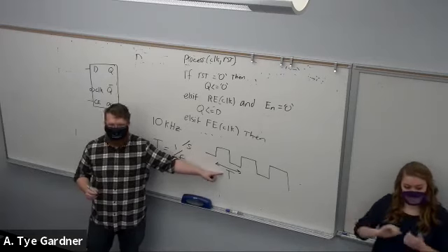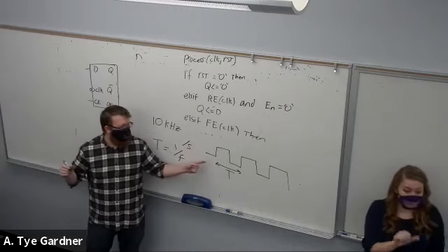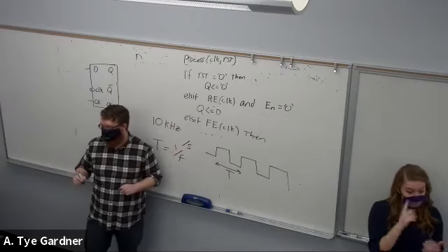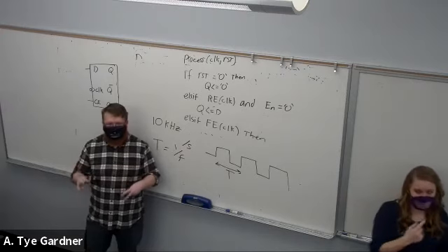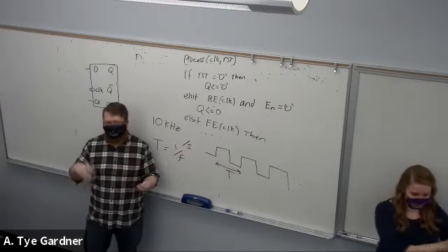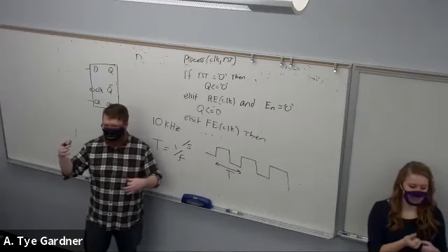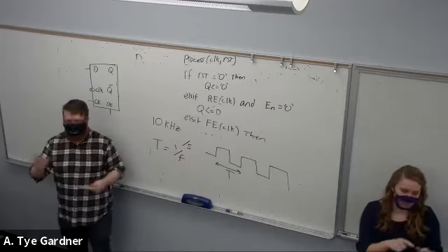That's why you can't write 10 nanoseconds. It doesn't know. But what you can do is count the number of clocks, wait for 30 clocks, right? That you can do. You have to do that conversion, and we'll talk about how we make different clocks and how we adjust the clocks. Mostly slow them down. In 3610, we'll talk about speeding them up because that gets harder. But anyways, this is where we're going next. Thanks for listening.